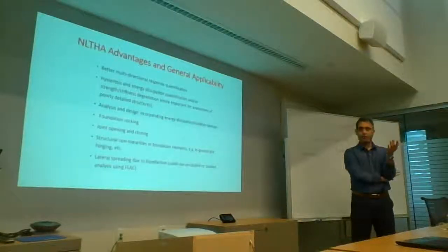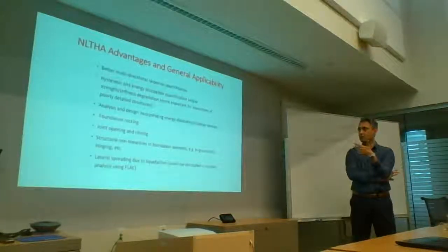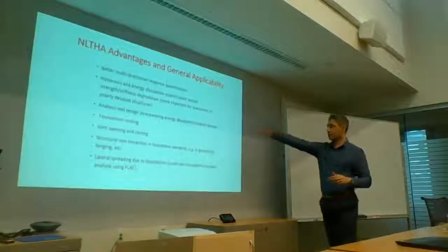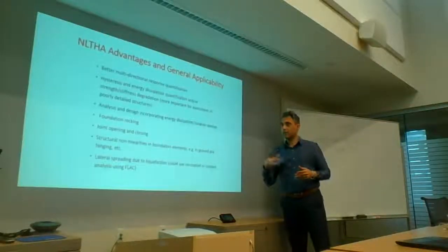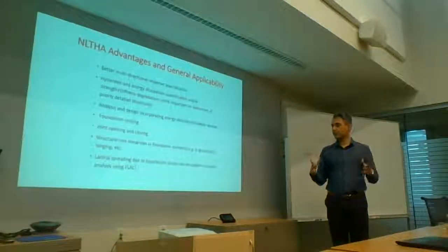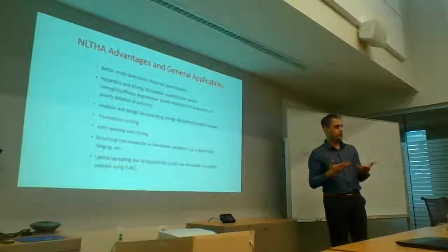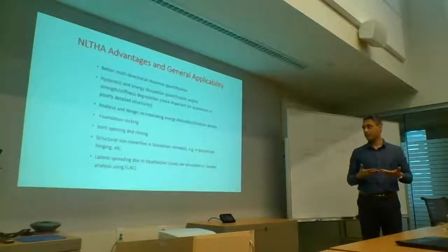And if you look at the code, under certain circumstances you can use a modal analysis. You modify your response spectrum based on your isolation devices, and you can come up with damping in your isolation devices that may be up to 30% to account for the fact that these are energy dissipating mechanisms.